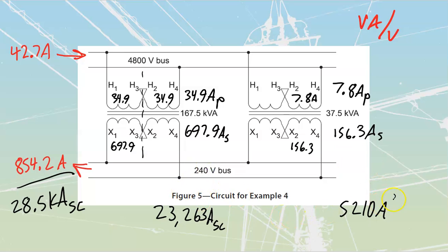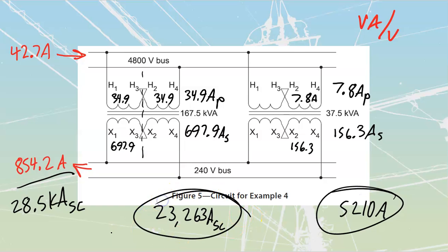Once again, the sole purpose of sorting these ones here is to make sure that we can engineer proper controls. Equipment, not just breakers actually, by the way, but even bus bar centers are going to have maximum fault current ratings. The reason for these is in a lot of cases going to be mechanical, because if I get 28.5 kiloamps, that's 28,000 amps, the size of the magnetic field around there is going to be absolutely astronomical. And if I've got a massive, massive magnetic field, that means it's going to repel from some stuff or attract towards other stuff.